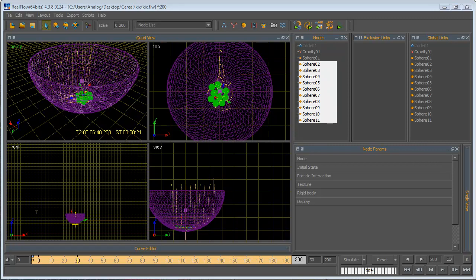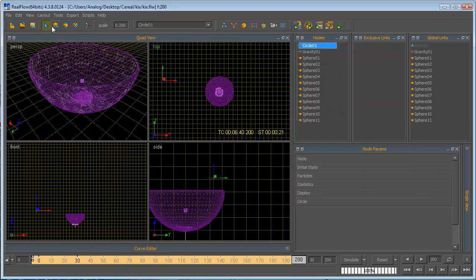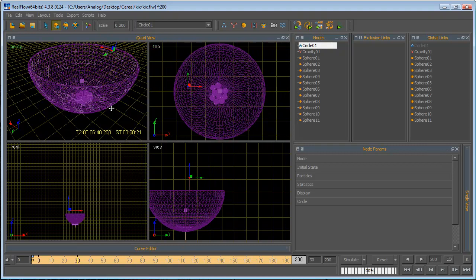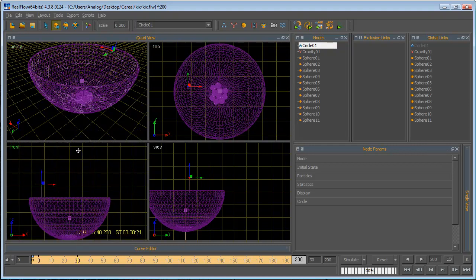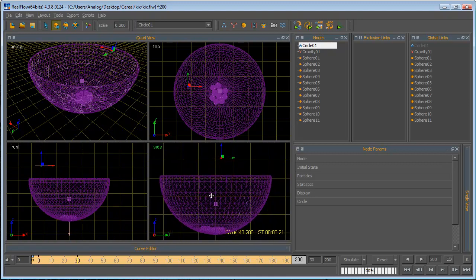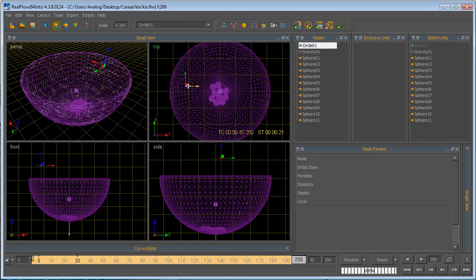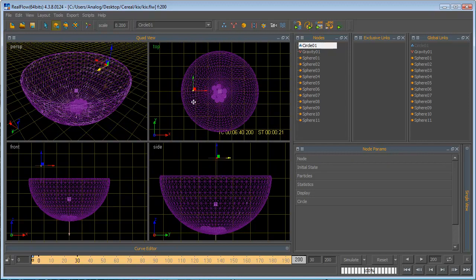We're back. So yeah, the initial states are good. Scale is 0.2. The emitter, it's right here. Well, it's actually way off to the side. Let's bring that over the bowl. And this is the fun part. I like this the most. This is when we start messing with the fluid. And right off the bat, I'll just tell you, a lot of it's going to be just visual, and there are some little tricks to messing with the liquid, but a lot of it comes down to just trial and error. But I'll show you some tips and we can troubleshoot the liquid a little bit.